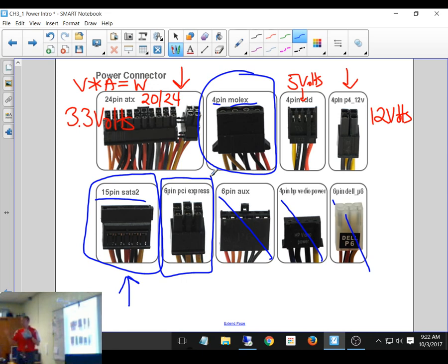That was the only time I've ever had one catch fire when I say that, but it just fries the components inside, it doesn't work anymore. Which is why this is a very common thing to go out. Because not just when you buy a new video card and put it in, do you forget to calculate it, but when you buy this system from Dell and say, I want this hard drive, and I want this CD-ROM, and I want this Blu-ray burner, and I want this sound card, and I want this video card, they very frequently never even change this. And I've changed a lot of people's power supplies that there's no way it should have even worked, in my opinion. Because when I did the calculation, I'm like, you needed a 450, and this is a 300. How the heck did it ever work?